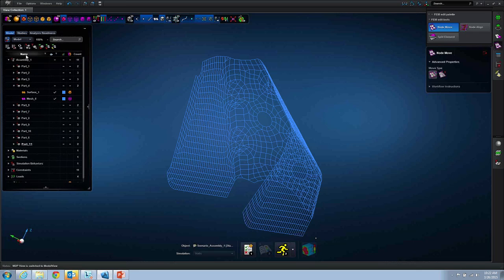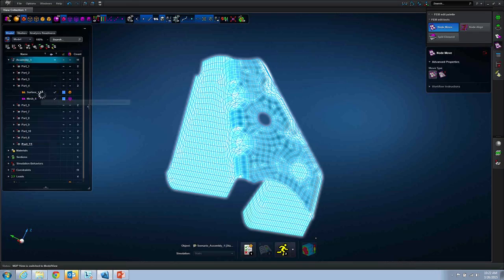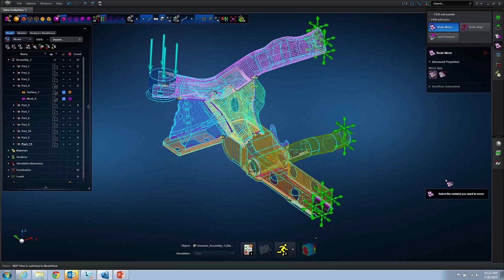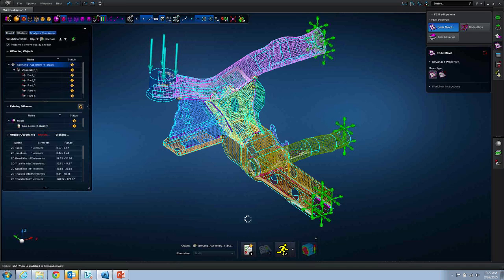Going back to this setting, show all, and take a look at it once before we run the simulation. Now I'm going to run the simulation, which may take about a minute and a half to 2 minutes. If you look at the bottom left corner, it is going through those 4 processes: generate, assemble, solve, and recovery of the results.